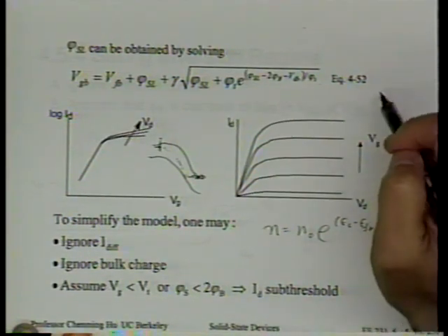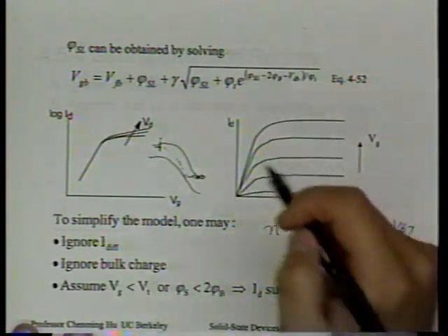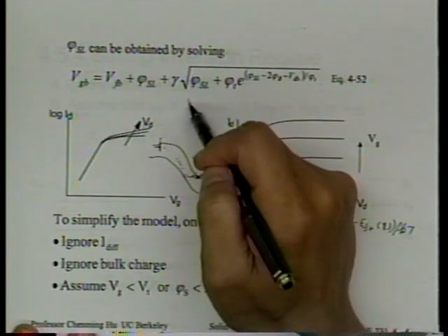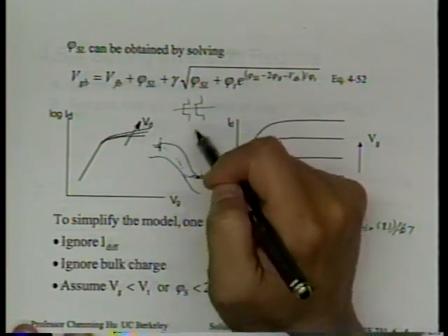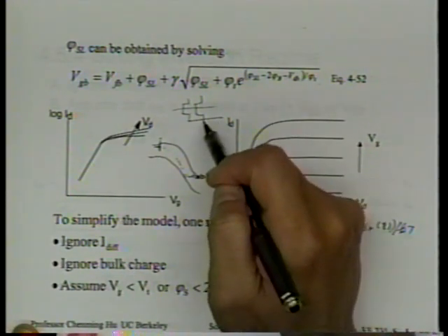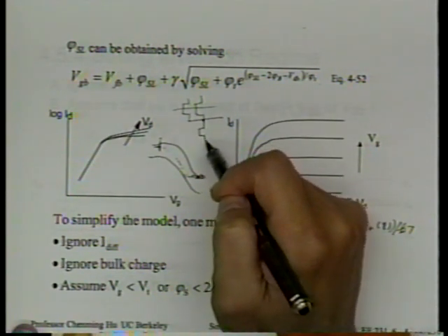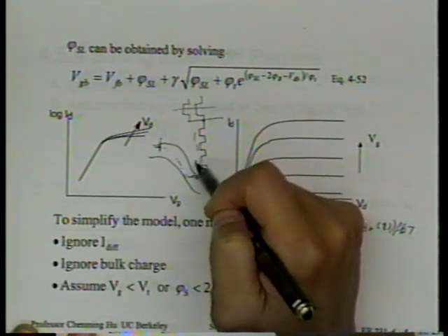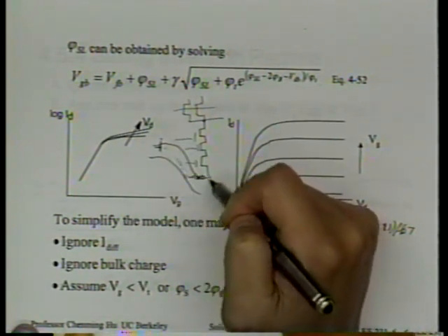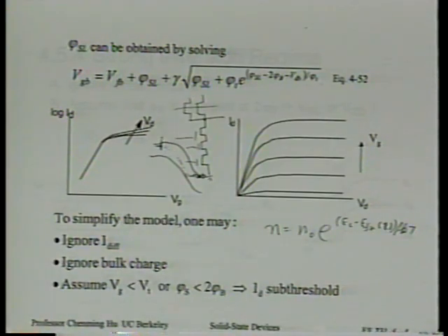It's for necessity. Think about a NAND gate. As you know, NAND gate will be made of several P-type wells, I will not draw the connection here. It's a bit complicated. Just look at the pull-down leg. You're going to have several N-type transistors in series, for example. Each of these is connected to an input of this NAND gate. This is called a NAND gate. This is one circuit, all right?